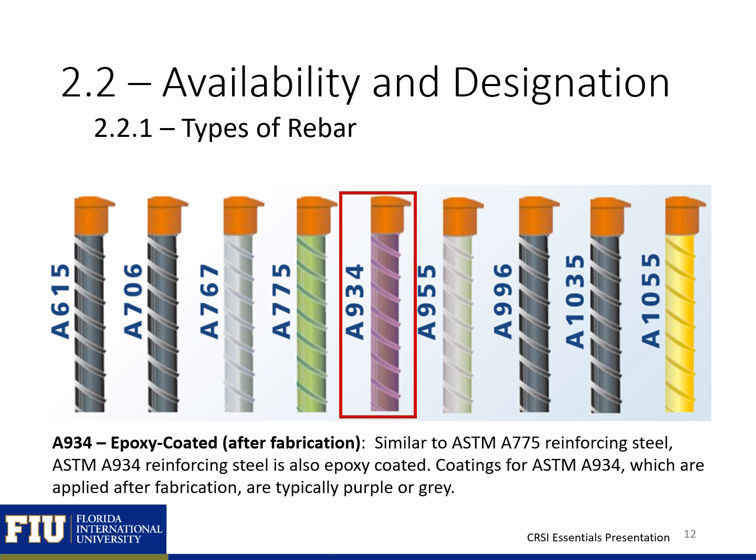Similar to ASTM A775 reinforcing steel, ASTM A934 reinforcing steel is also epoxy coated. Coatings for ASTM A934, which are applied after fabrication, are typically purple or gray.